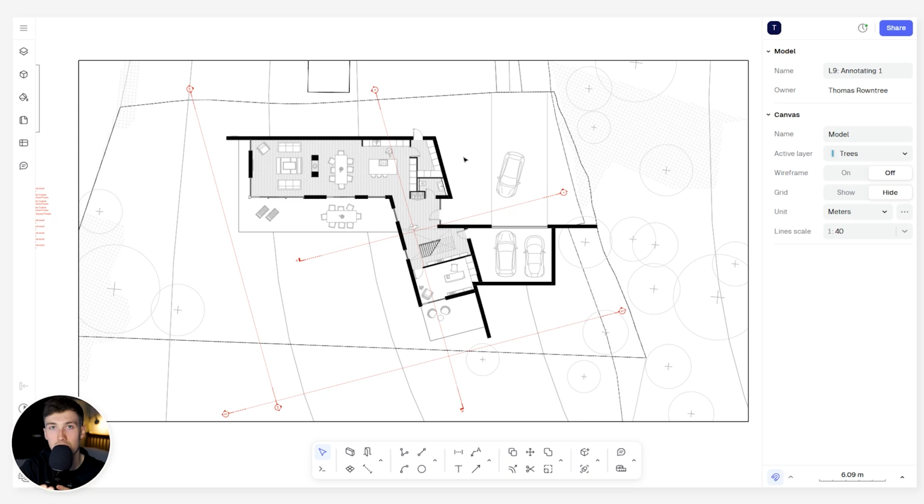You have the drawing itself, which is in black and white, and then you have the annotations, which are in a separate colour, so you can differentiate the information between the two. And this will be a fine balancing act of not overwhelming your drawings with too many annotations, not having too much colour, etc. So there's a fine balance.